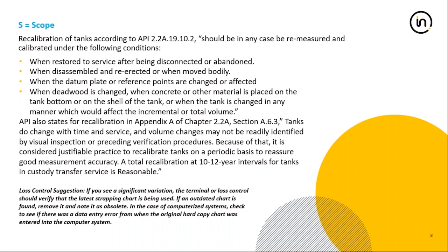The reason why we do this is because the API also recommends that you have your tanks inspected every 5 years. And what you do in these inspections is you go out and you measure some of the rings and you measure the wall of the tank, and you do most of the work that a complete recalibration would require you to do.